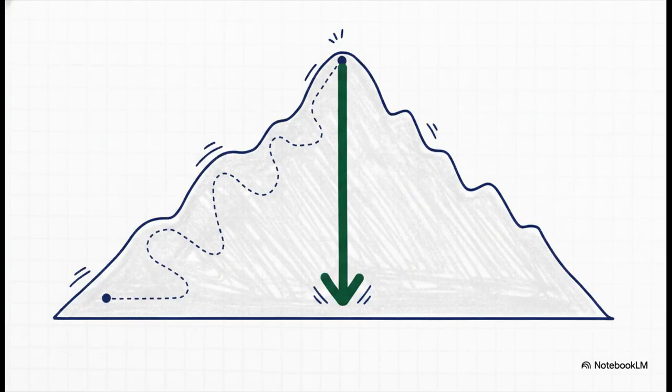Now, the LMS algorithm is awesome, but if your starting point on the mountain is super far away from the bottom, taking small steps based only on the instantaneous gradient can mean incredibly slow convergence. That's where the recursive least squares, or RLS algorithm, comes to the rescue. RLS is mathematically much more sophisticated. Rather than just moving down the instantaneous gradient, it recursively updates the inverse of the deterministic correlation matrix itself. Because it's constantly refining this inverse matrix on the fly, it adapts incredibly quickly and completely overcomes that slow initial convergence we see with LMS.